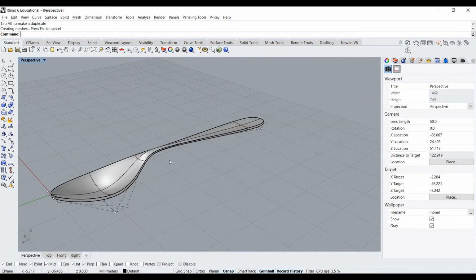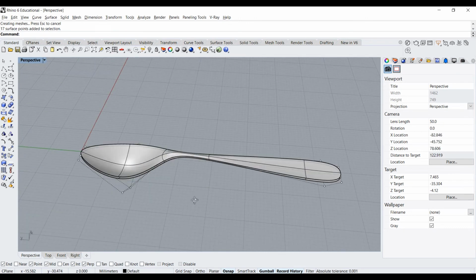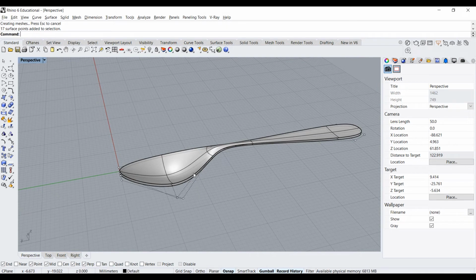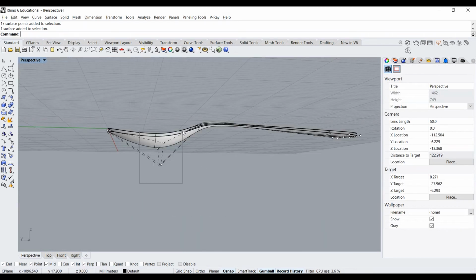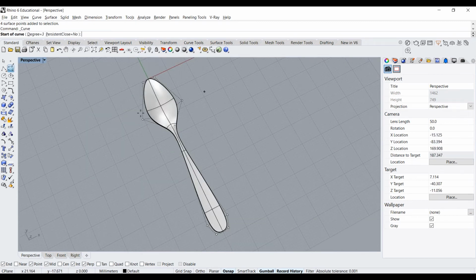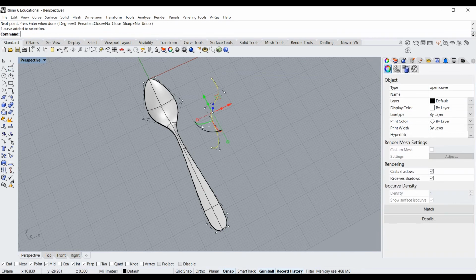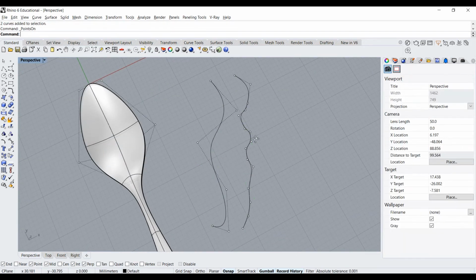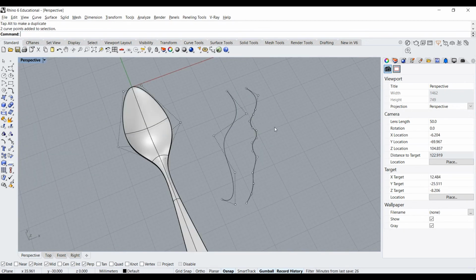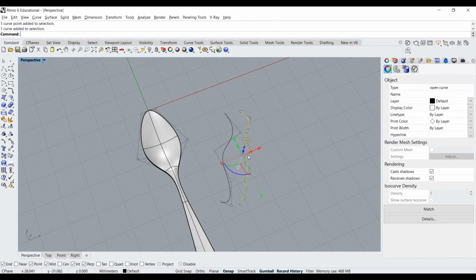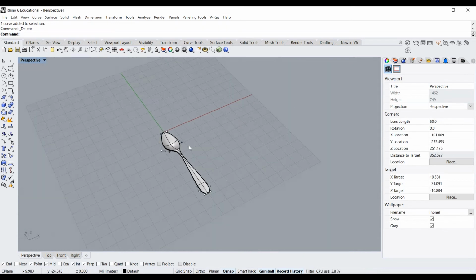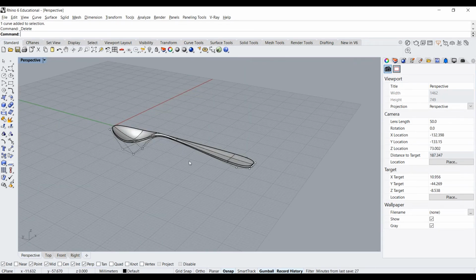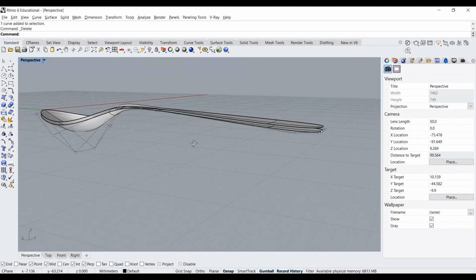So you really can be as detailed as you want, and this is a very simple surface. There's not very many control points in this. You can imagine if you had a very complex surface, you might have more points. But interestingly enough, counterintuitively a little bit to some people, you want your surface to be as simple as possible. You want as few control points controlling the object. Same with a curve. So actually remember when I drew this curve, I used a very few number of control points. You could draw the same curve with lots and lots of different control points. But the problem with that is that once you try and point edit that, you end up with hundreds of different points. You end up with a really horrible, messy surface. So less is always more when it comes to NURBS. You always want to have as few number of points in your curves and surfaces as possible to get the best results. And this is to do with the way that the maths works, but also just the practicalities of having to edit lots of points or just a few.